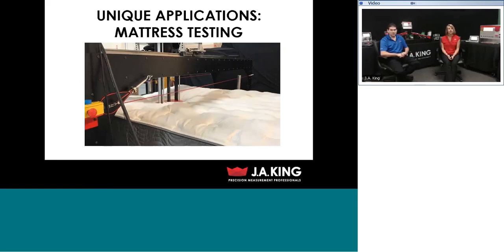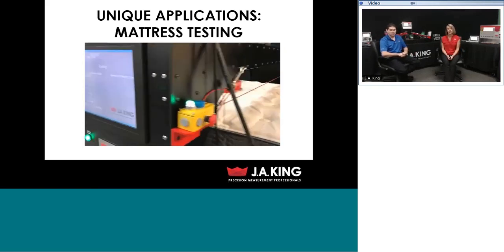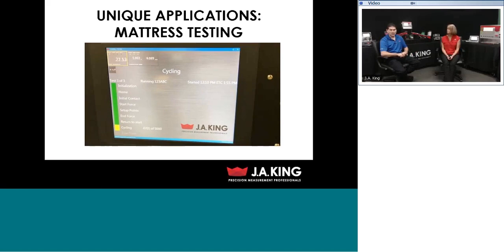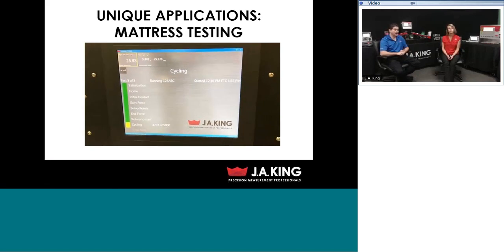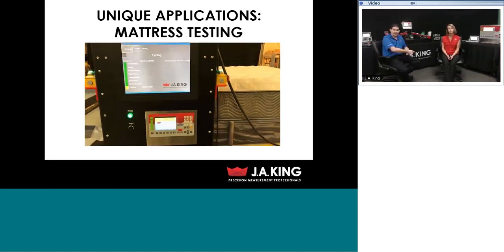This one happens to be a Cornell mattress tester, so it's doing mattress longevity testing. Yeah, this system here is Windows-based. We wrote custom Windows code that controls most of the operations on there. That ram is hitting down into the mattress 100,000 or 200,000 times, depending on which life cycle test. There are load cells in that head, and we brought those load cells into the programmable indicator, and it's logging the pressure wave that it forces down into that mattress. So it's capable of generating a force curve based on each stroke. They use this data to determine the degradation of the mattress over time.